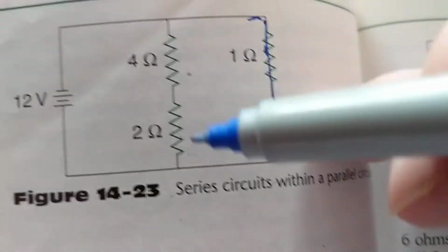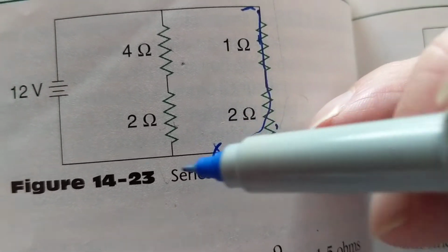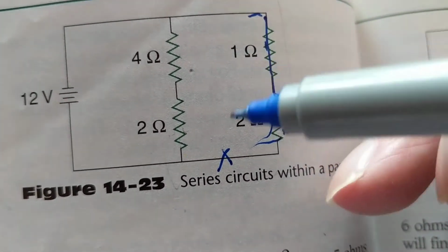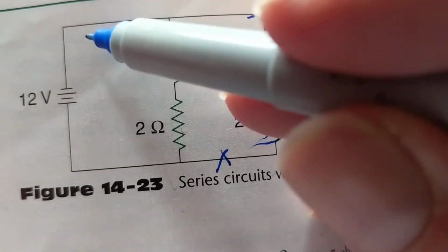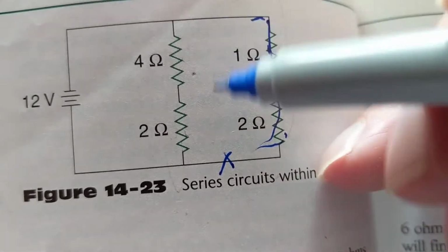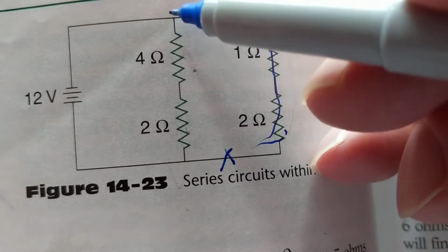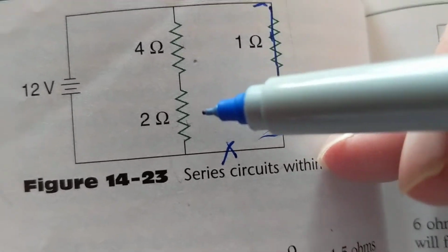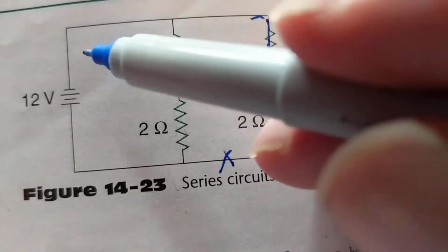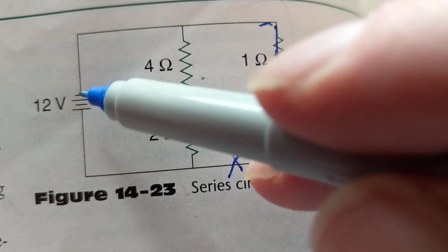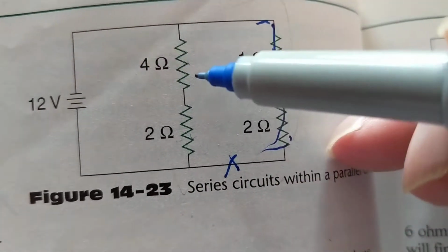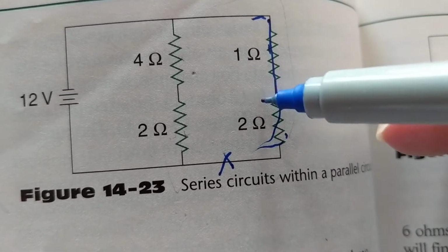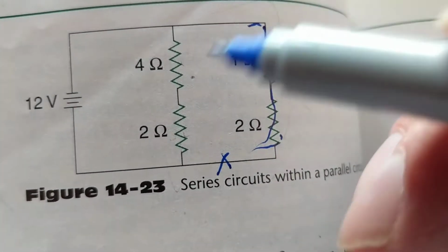Okay? Let's say the open is here. Uh-oh. Open is here. Can current flow here and here? Current can still flow here back to the battery. The rule is in effect. As long as I have a path to go back, I'm going to use that one. The current doesn't care which one it is. It just says, give me a path to go back from point A to point B. I'm happy. He goes here. Of course, the resistance changes because now we have less than this 3 ohms together. Like I said, we're not concentrating on that.